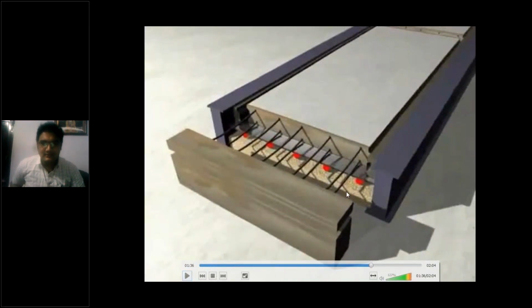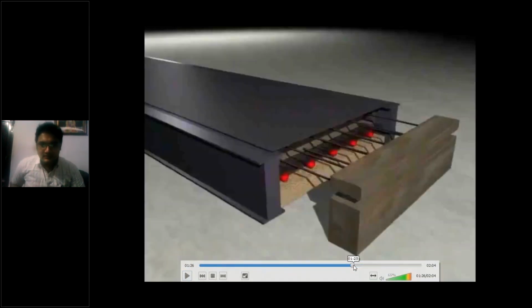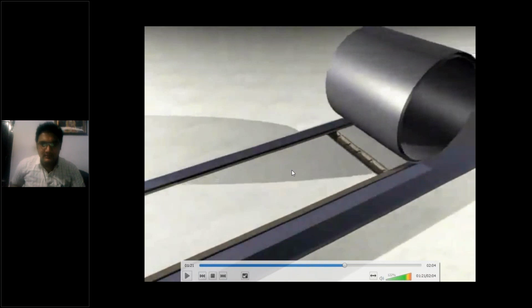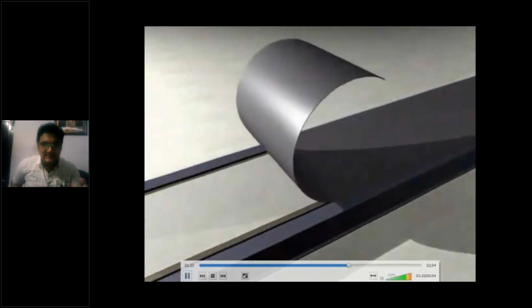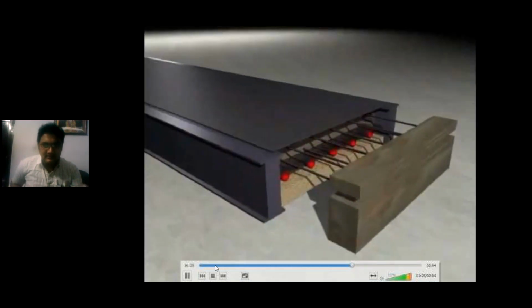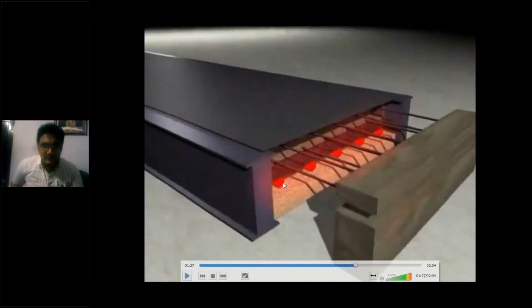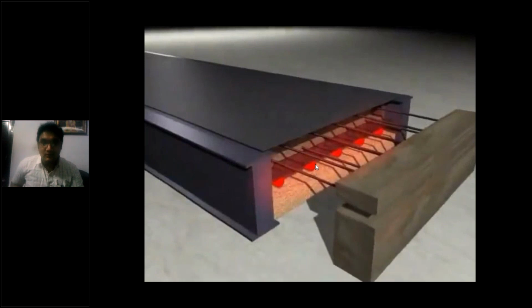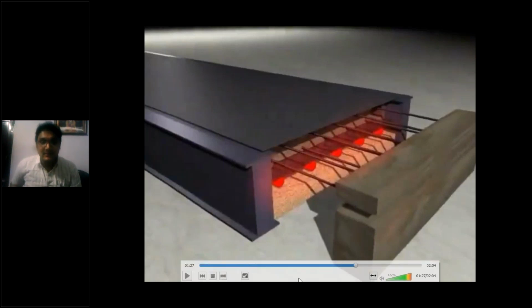See what they did now. What is this, something laying on the surface with some red sparks? Why are these rods red in color now? They are heating the rods. With that, steam will be generated. Through that steam, the concrete will be cured fast, it will set fast. By that you can remove the mold within time.